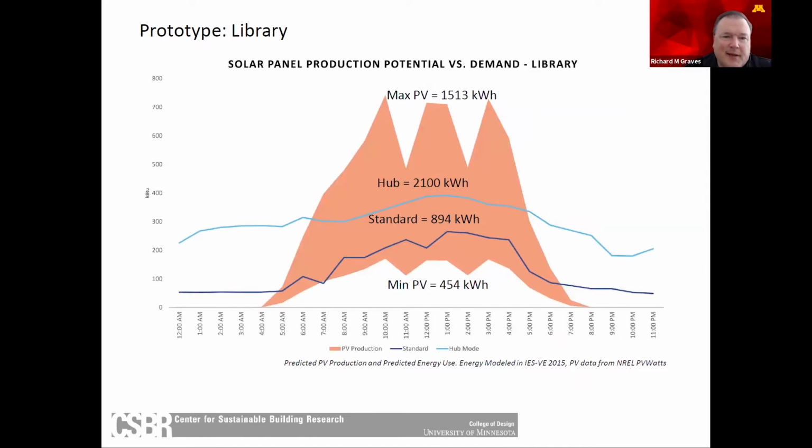So in this case, what's interesting is, again, energy usage goes up. This is a building type that isn't as dense. It has a lot of roof area for the amount of occupancy, so it would be fairly easy to achieve net zero with solar on the roof. In fact, you wouldn't even need to cover the entire roof with solar panels. But when you start to think of an operating mode as a resilience hub, maybe you increase the amount of solar on the roof so that you can recharge more batteries and take care of a larger need in case a disruption occurs, and that becomes a key element of a neighborhood resilience strategy in this case. So next slide.